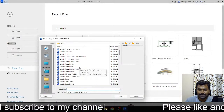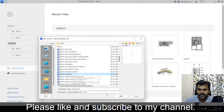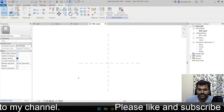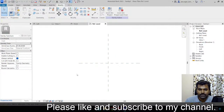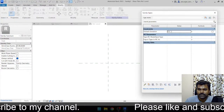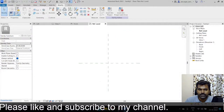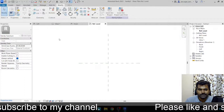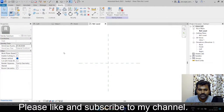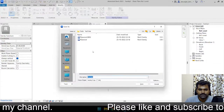Okay, let's select metric furniture template, open. Okay, so this is our furniture template. Go and select family types, just to check what is there already, so that you can change it later. Okay, general furniture omni class number is applied, that's fine. There is nothing else, so just have to save it.